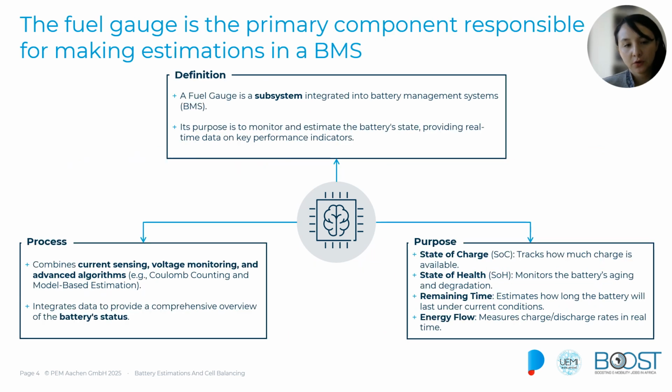And before doing that, maybe we will explore one of the key components that is responsible for doing all of these estimations in the battery system, and this is the fuel gauge. The fuel gauge is going to be a subsystem in our BMS. It can be either an electronic component or a component that is integrated in the firmware of the BMS.